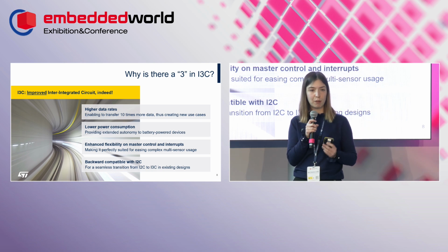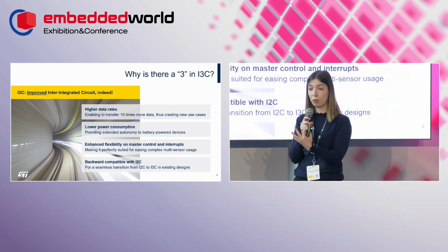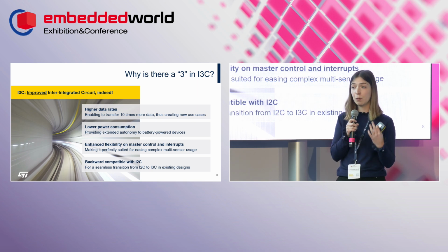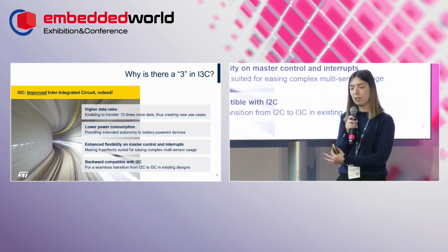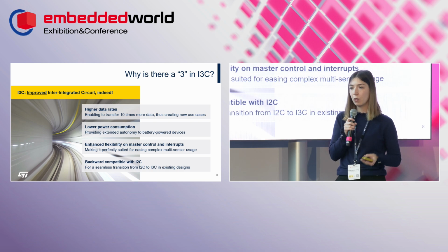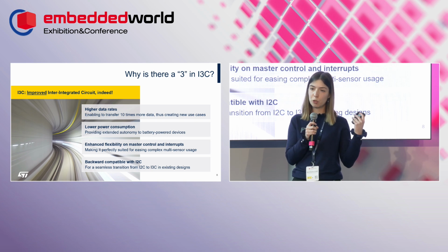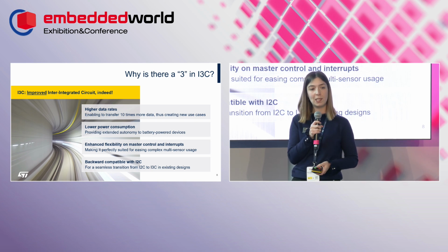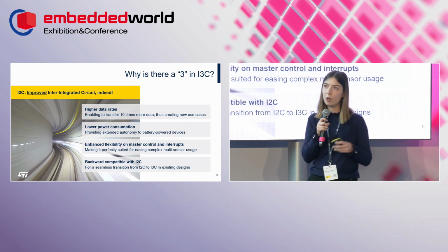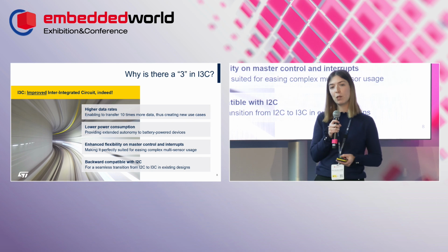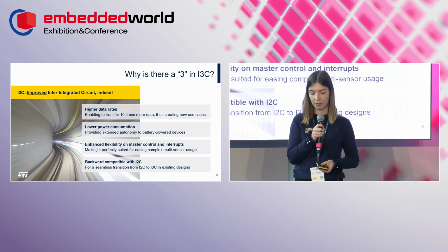It is very important if we think about the main components to put in a vision system, which are the sensor and the processor. There are a lot of microcontrollers today equipped with I2C, and more and more equipped with I3C, and this is made possible by the backward compatibility. So with I3C, a first good point is that it opens the door to the use of microcontrollers in vision applications. You got the example right before of the STM32, but there are more and more. So I3C: higher data rate, lower power consumption, more features, and the use of microcontrollers is now possible for embedded vision.